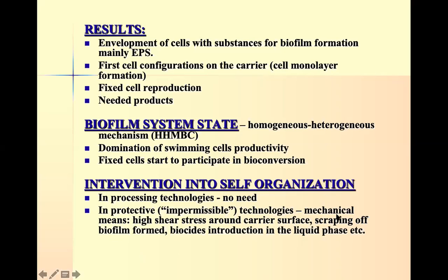In protective technologies, mechanical means, high shear stress around the carrier surface, scraping off biofilm, biocides, introduction in the liquid phase is necessary. Otherwise, that means if you want to protect the surface from the biofilm forming bacteria, then you need to use biocides, or some other means, increase the shear stress, so that organisms cannot form biofilm and damage your surface. So these are the results.